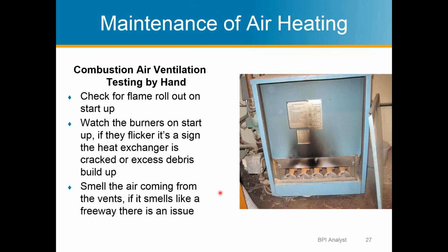All right, so some other things to check for. Check for flame rollout on startup. If it's been happening, there are usually signs that you will see, and that's what this is here. It's a little sign of flame rollout. That's just where it's been burning the front of the furnace. When you start the burners and you're watching it do its startup, check to see when the blower motor turns on.